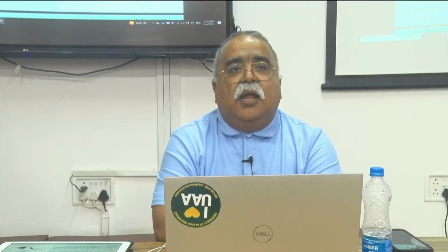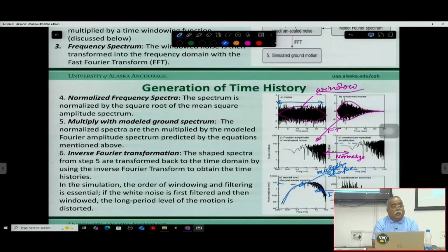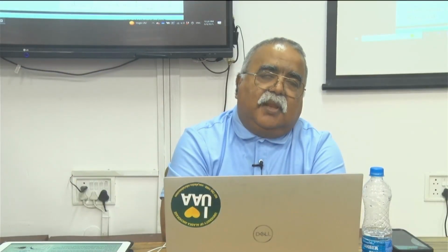Now this is only once, right? But the generated earthquake depends upon your random noise, meaning how you select that random noise, up to what frequency, depending on the frequency of the noise. I have generated all the frequencies possible, because the random noise is random noise, so it does not need to have any particular values. It is just amplitude values, and whatever amplitude has been generated will be converted to the frequency domain by taking the Fourier transform of this one.